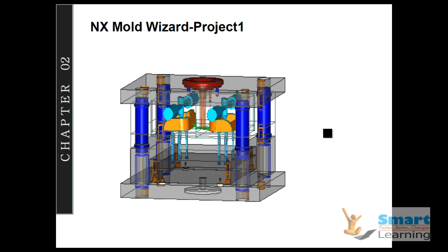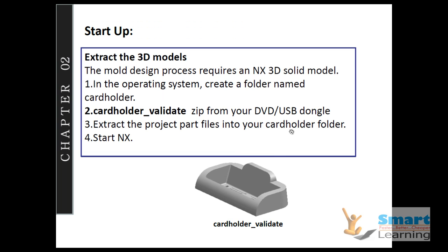By using this particular project, a multi cavity with two components which are flipped, you can see the principles for spruing and how to allocate the risers, runners, and complete mold base.